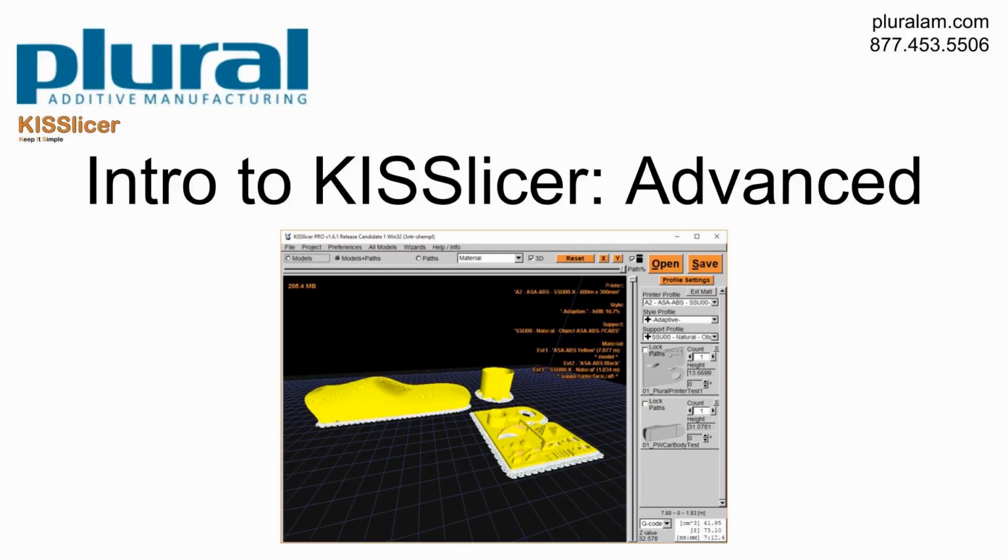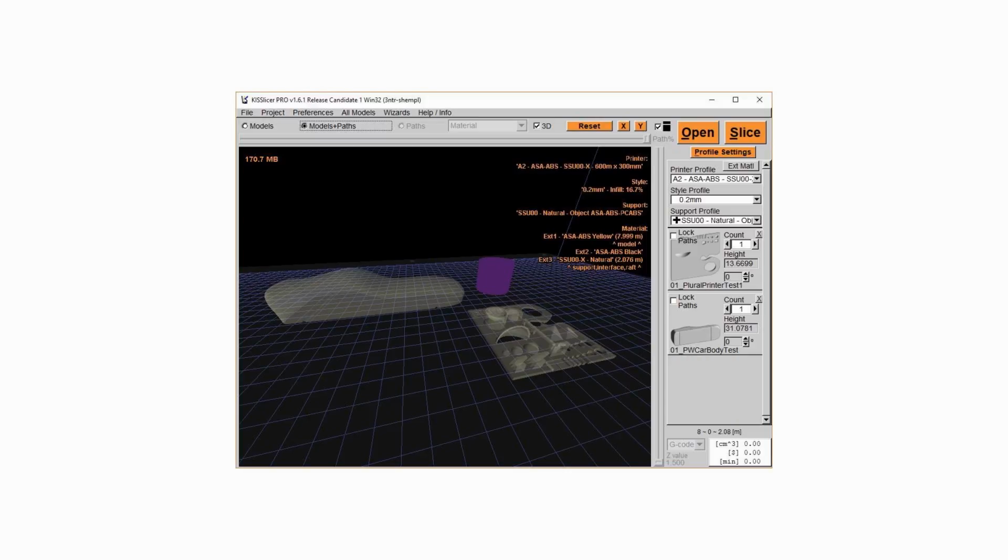Hi, this video will cover KISSlicer's advanced settings level and wizards. First, besides slicer settings, additive manufacturing designers and 3D printer operators need to be aware of the impact of print orientation on 3D printed parts. If surface quality was the primary concern for this print, the car should be oriented so its nose pointed straight up, minimizing the stepped surface effect that comes from subtle curves through the Z dimension.